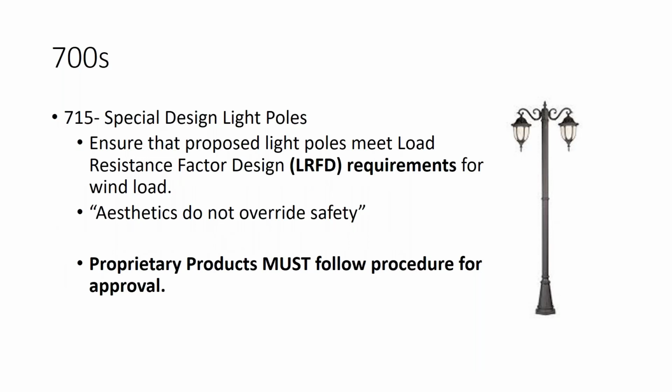715 addresses our highway lighting, and specifically we want to draw attention to our special design light poles. Designers should ensure that the proposed light poles meet load resistance factor design, or LRFD requirements for the wind load.